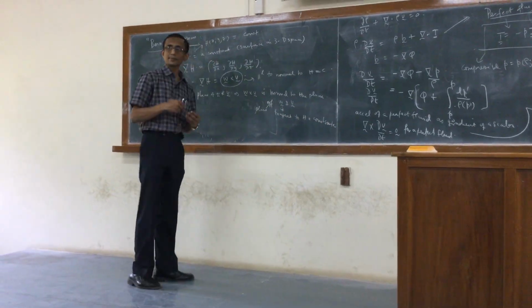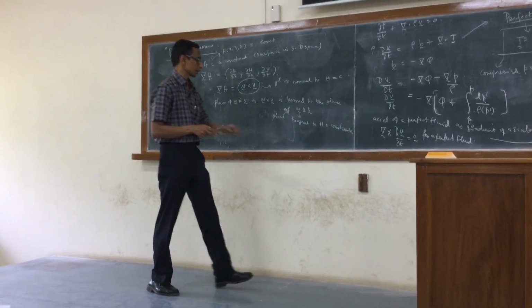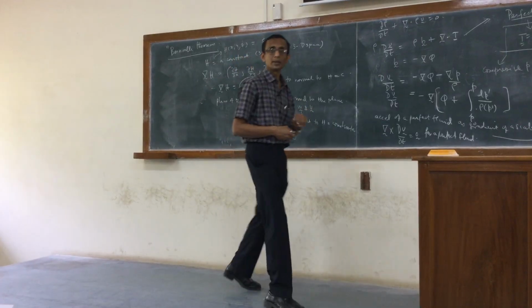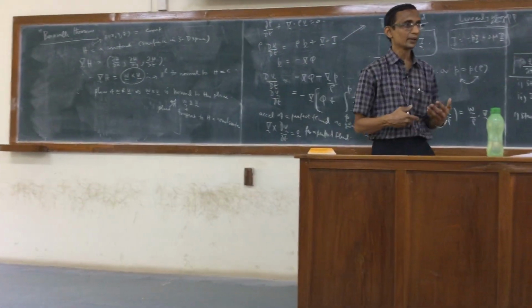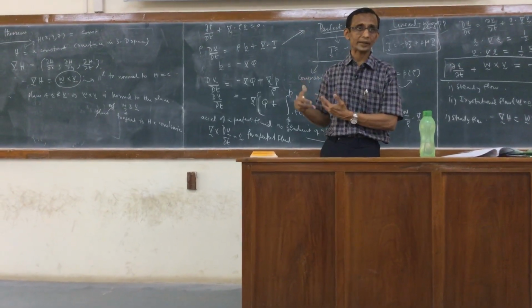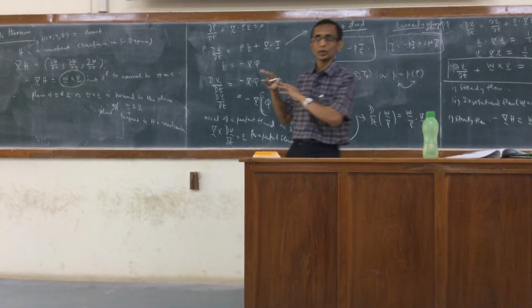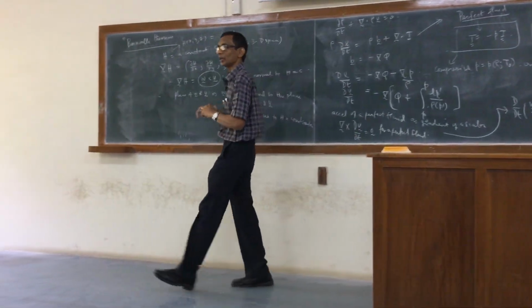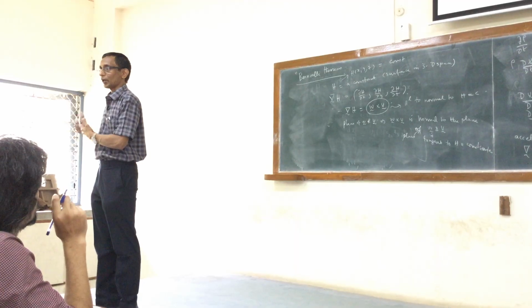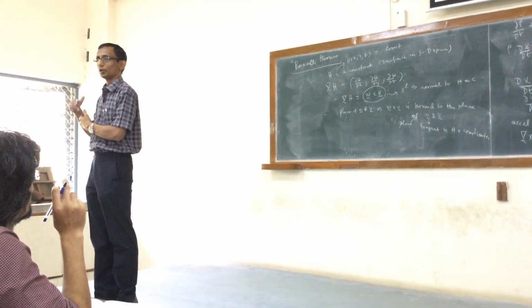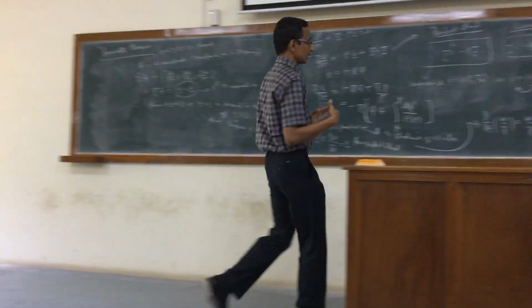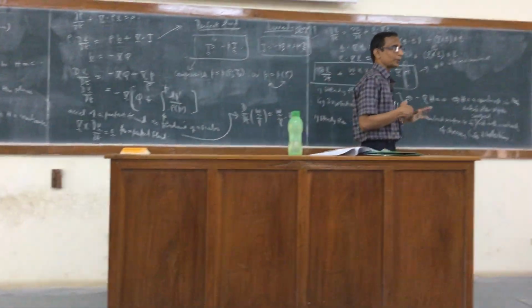The reason why he says it's a network of streamlines and vortex lines is that we know the tangent to the streamline is given by the v vector, and the tangent to the vortex line is given by the w vector. What we have already shown is that the plane of w and v is acting as a tangent plane to the h equal to constant surface. So we need to go a step further and prove that this kind of argument leads to a point, but I don't think it proves it.